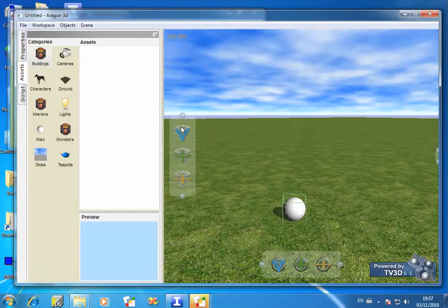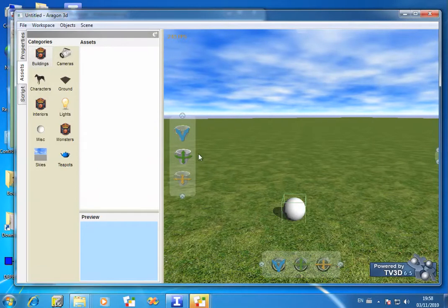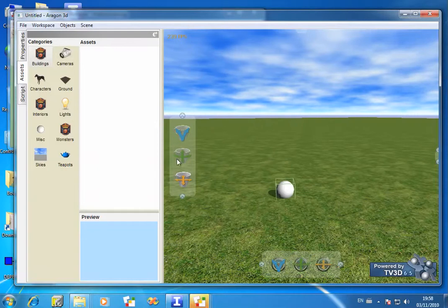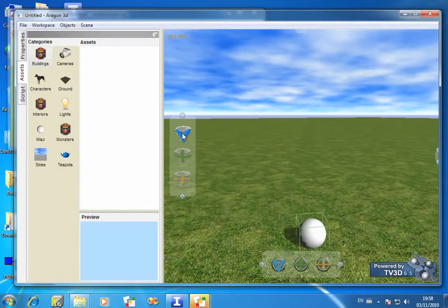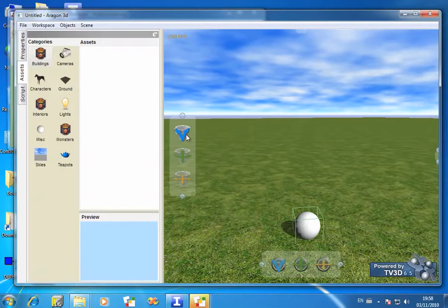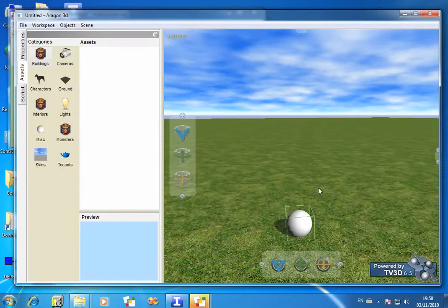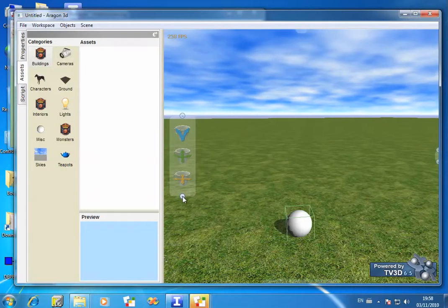Once again, I can pin these to the screen, and these will manipulate the selected object. I can rotate it, I can move it, and I can dolly the object. Okay. Once again, these respond to the Alt key to give movements in the alternate direction. Okay, those are the basic manipulation functions for objects in the 3D window.